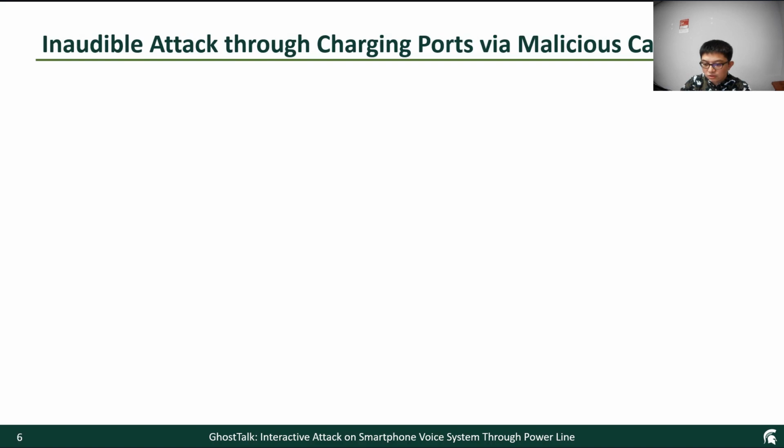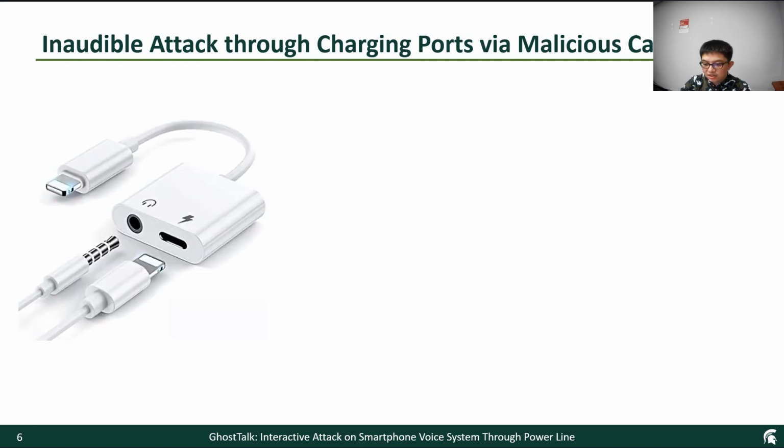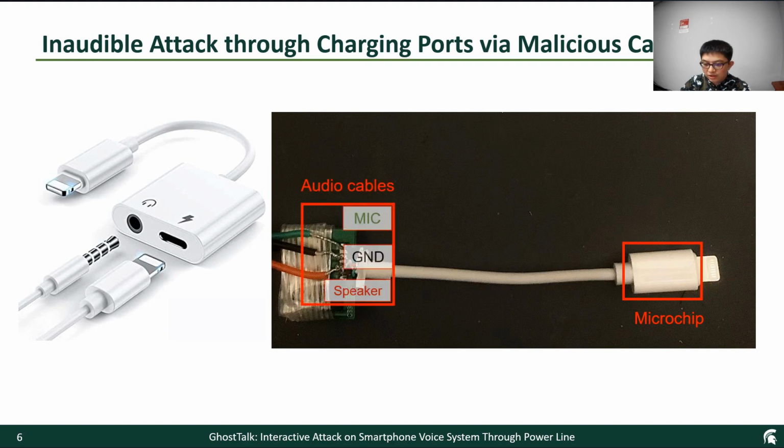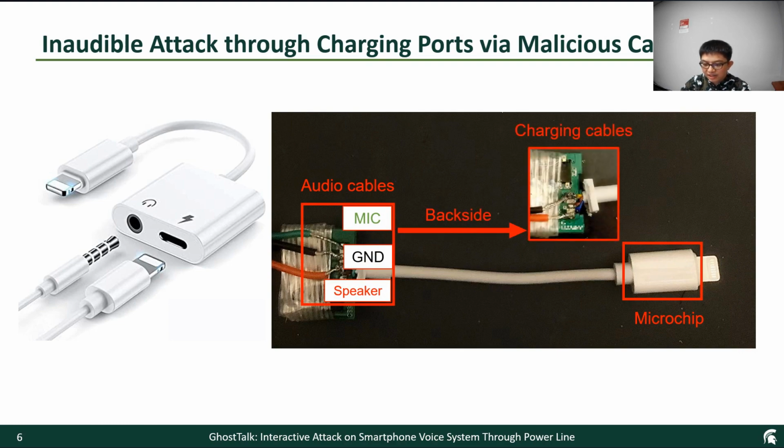Furthermore, we find out commercial adapters are designed for using headphones while charging. Different from standard charging cables, the microchip in the adapters enables audio transmission. Next, we disassemble the adapter. We see that there are audio cables, including microphone, ground and speaker, and charging cables. If some attacker can replace the standard charging cables with this malicious adapter cable, they can launch a new inaudible voice command attack by manipulating or monitoring the electric signals on the microphone or speaker.